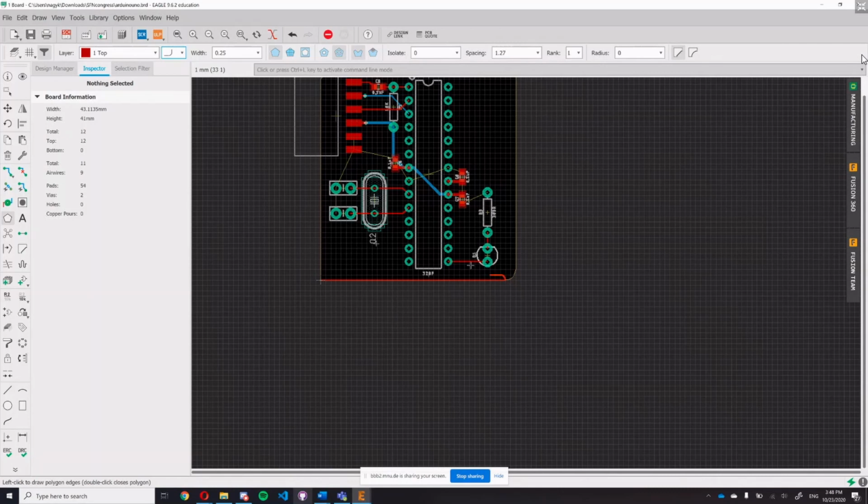Well, sometimes you cannot eliminate them, because imagine that there would be 10 different components laying over each other, and sometimes you just don't have a mathematical way, or geometrical way rather, to eliminate the crossings, because all the lines have some width, and sometimes you just cannot go around. So what you do when you cannot go around, you just add another layer. So now we have 2 layers, but you can have another layer in the middle, but you cannot do that automatically. I hope that that's the answer.